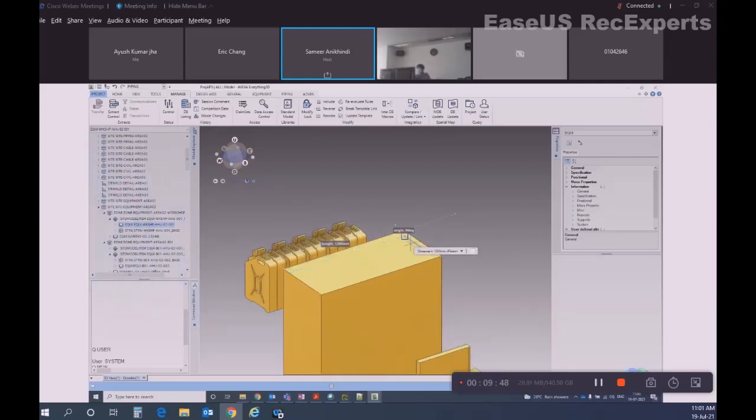Angle 0 degree, it is specifying. Press B, enter, so it will go back to the previous. If you press B 2 times, it will go back 2 stages. You can keep on pressing B, enter means back. So DI is for distance. M is for move. CO is for copy with base point. ID is for measurement of coordinates.